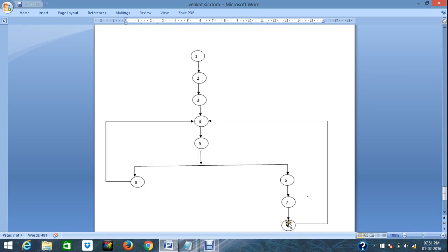Then what happens is, the control again goes to comparison of rotational speed of individual wheel. Here also, after again going to this fourth stage, it will again check whether lock is detected. If again detected, the cycle repeats.